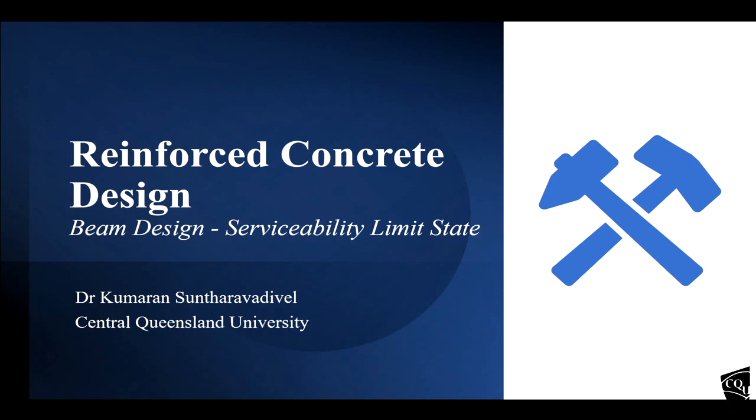So we assume some depth. We assume a depth of the beam. Then we do a deflection check to ensure our assumption is reasonable. If it is passed, then you can proceed to the reinforcement calculation, so that you don't have to repeat the whole calculation again. So the deflection checks are important. We will look at the serviceability limit state checks first, and next week we will look at